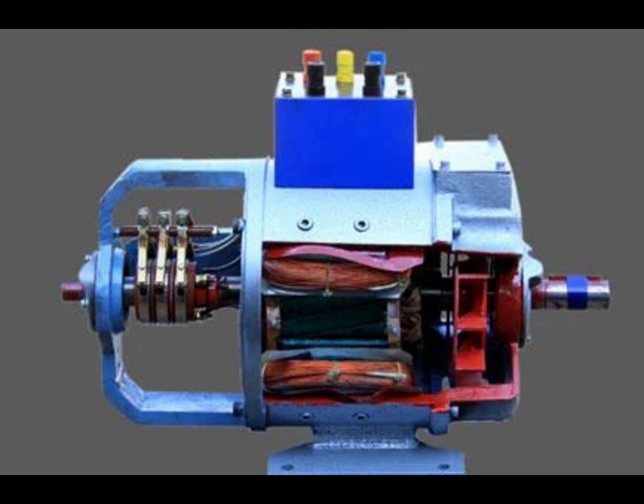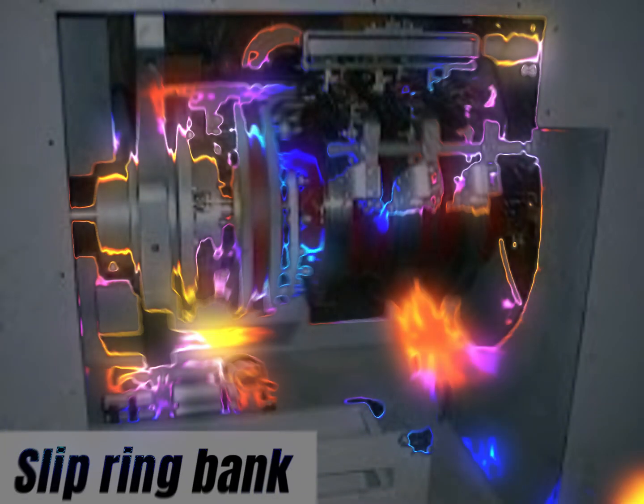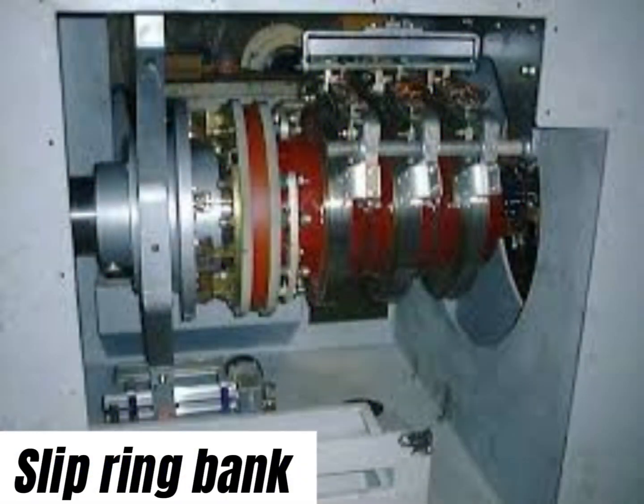The current inrush on starters with 2 steps of acceleration is limited by the secondary resistors to a value of approximately 250% at the point of initial acceleration. Resistors on starters with 3 or more steps of acceleration limit the current inrush to 150% at the point of initial acceleration.